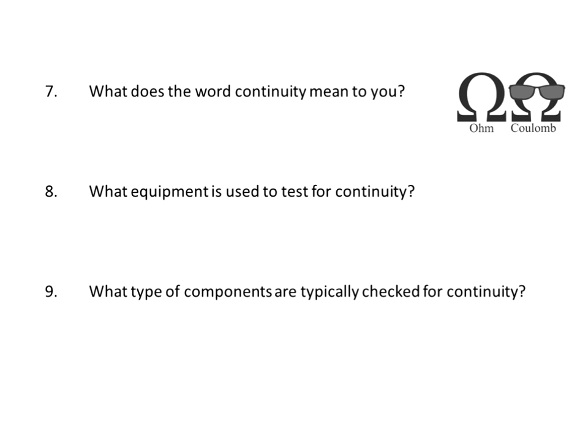Now, what kind of components will you check for continuity? Well, not only do you check for the connection of two wires, but it's very, very common to check transformer windings on the primary and the secondary with a continuity tester, because what are those made out of? They're made out of inductors. And what are inductors made out of? They're made out of turns of wire. So what do you read when you measure the resistance across a bunch of wire? Well, you're going to read some low number of ohms. It's called a continuity check.